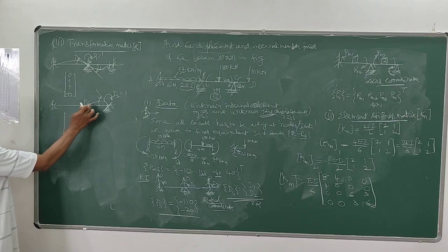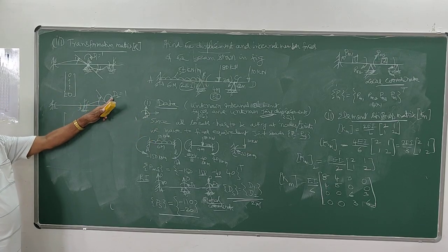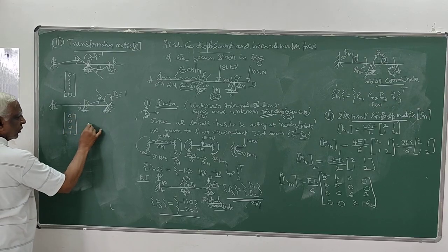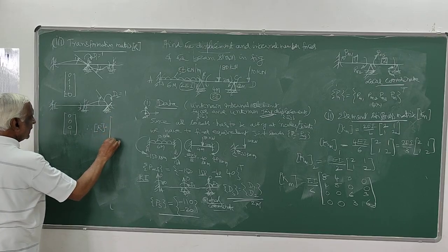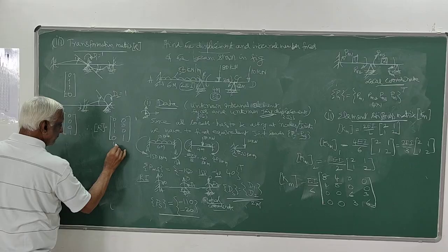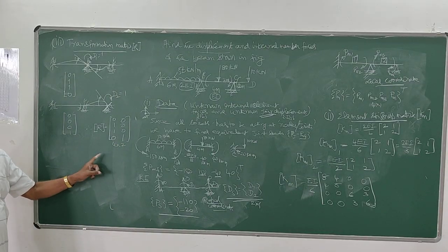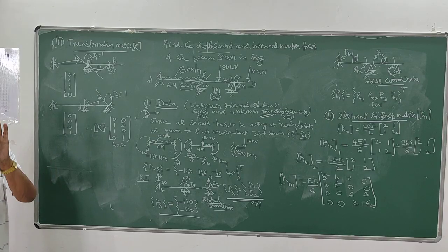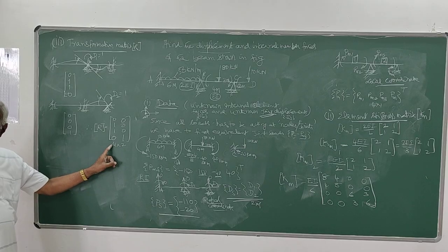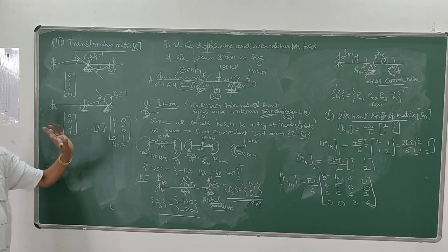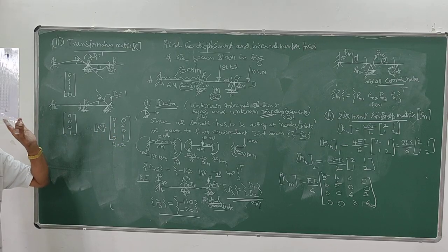So here, the displacements corresponding to local coordinates, when you give unit displacement along this global direction, are 0, 0, 0, 1. Therefore, your whole matrix will be a combination of this: 0, 1, 1, 0, and 0, 0, 0, 1. So it is a 4x2 matrix. I told you, Rij is defined as the displacement corresponding to member coordinates. There are 4 member coordinates, when unit displacement is given along a single global coordinate, that is coordinate 2. So this is very important.